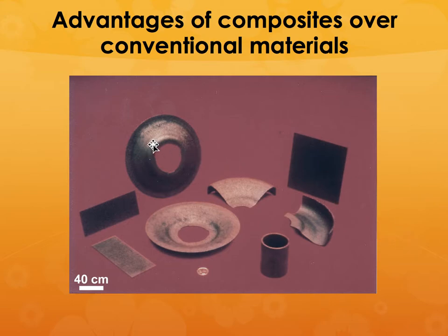For example, one of the earliest applications for these materials was for use as a flame holder from a turbine engine. As the flame is coming out, if you have a metal component, that metal component can easily melt away completely. But if you had a ceramic composite, especially one which had very good thermal expansion coefficient capabilities, then it can easily withstand the flame and allow these parts to be held together multiple times.